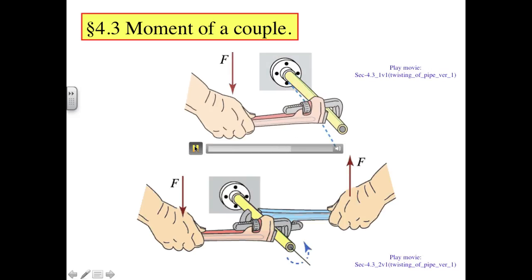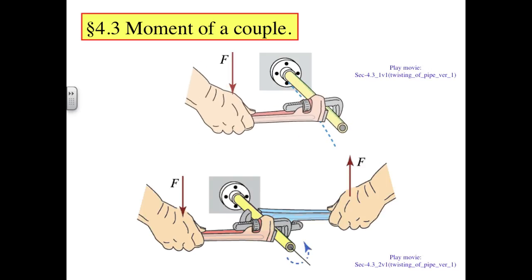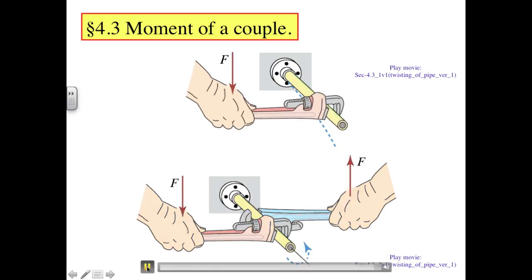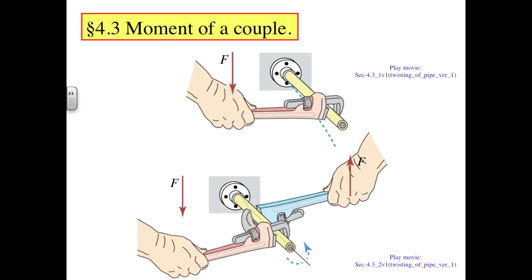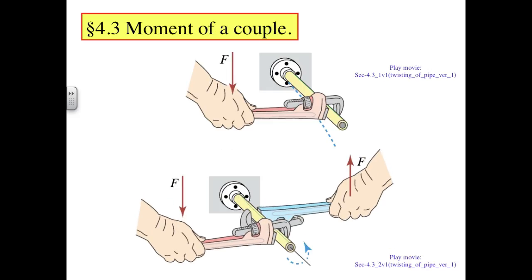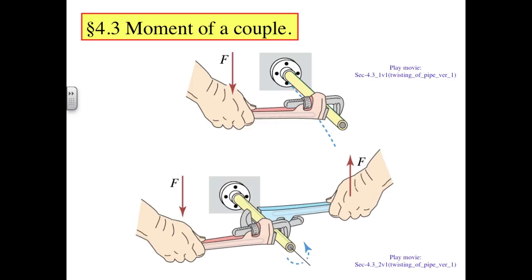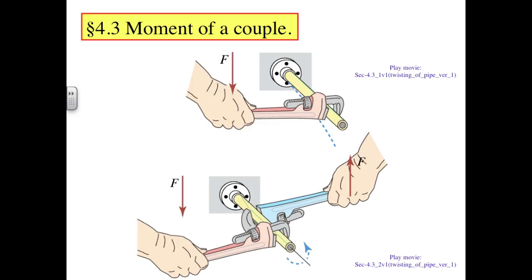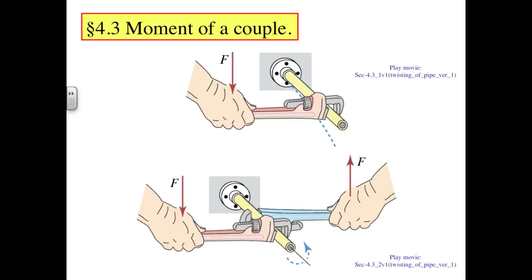As a reminder, this combination of bending and twisting is what happens when a worker applies a force through a single wrench. When the worker applies forces that are equal and opposite on either side of the pipe, it tends to be a much more pure twisting kind of moment. In this particular illustration, the jaws are separated by some distance along the axis of the pipe, so there actually would be a little bending involved in this particular application as well, but it's mostly just a twisting moment.